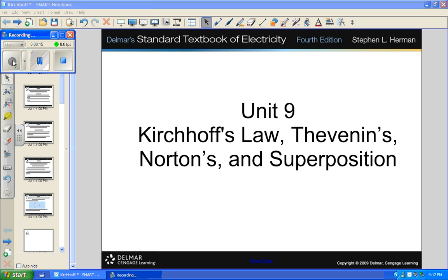Kirchhoff's laws, by the way, you've seen the little sticker that you can get from Mike Holt and a lot of other guys. It has 900 Ohm's law formulas on it, right? And you don't need those anymore because you know the pie chart and the two laws you derive from that. You can get anything from those laws right there: Ohm's law, and then the two derived formulas, P is equal to I squared R, and P is equal to E squared over R. So with those, you can do anything.